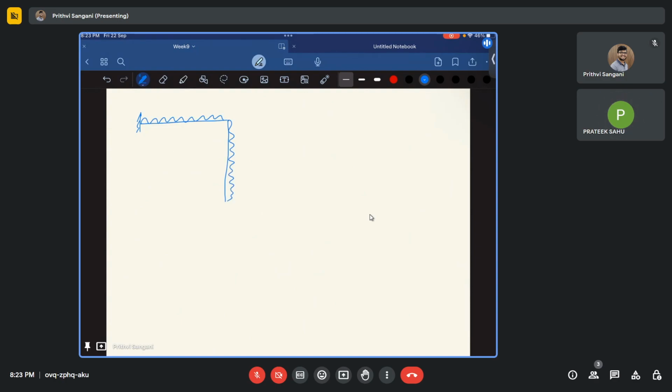So if you want to find the horizontal displacement, or sorry, the vertical displacement at point C, what you'll do is you will remove the external loads. The external load is the UDL. You will remove the external loads, and you will apply the unit load in the direction in which you want to find out the displacement. After this, you will find out the bending moment in both the beams, so in both the frames.